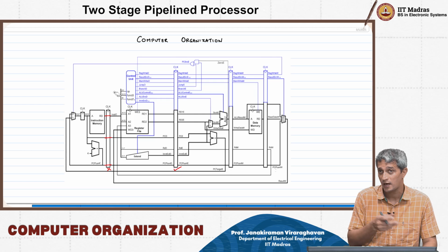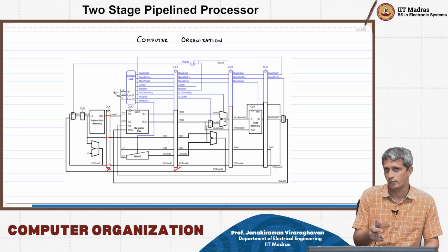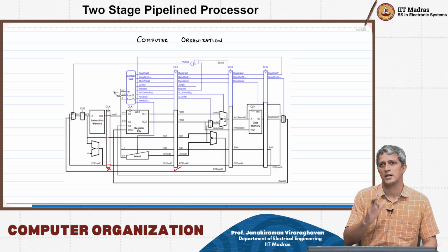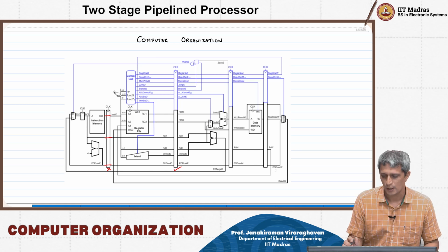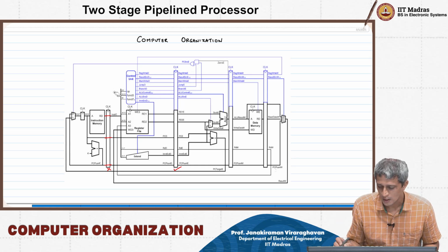It doesn't help us understand control signal flow through a pipeline. So therefore, deliberately I am choosing the flip-flop after the register file as the only flip-flop in this particular 2-stage pipeline system, right? And of course, the design is not going to be very different. You're going to have signals just flowing through it like that.